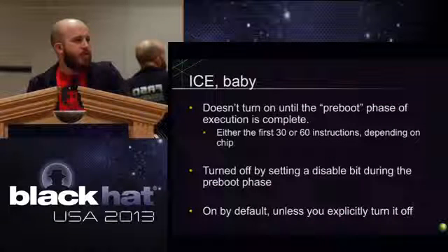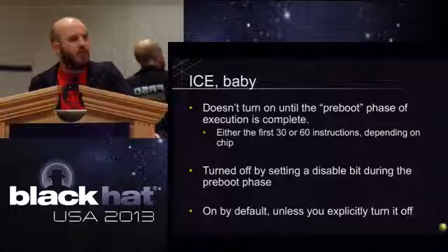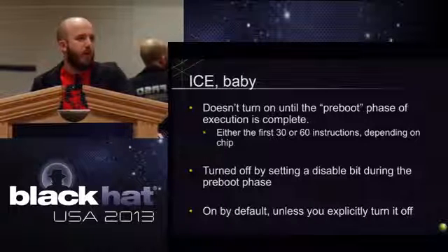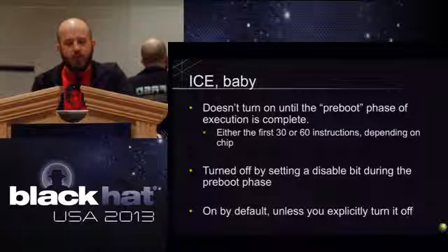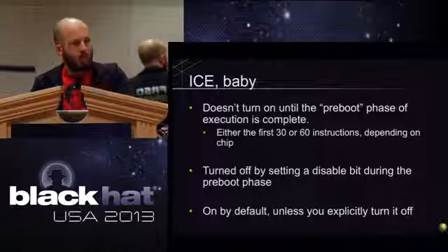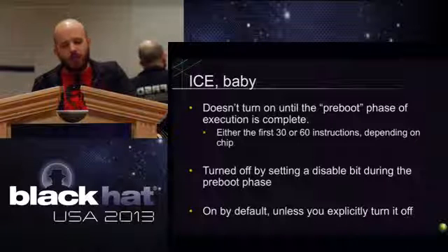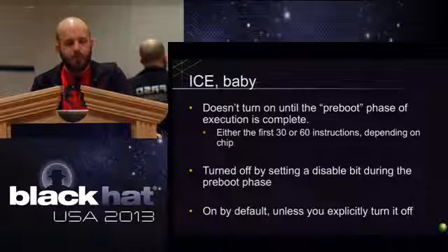So the way this works, you think about JTAGs, right? You know that JTAGs have these fuses, and you can blow a fuse, and then the JTAG interface is now turned off. In this case, it doesn't quite work the same way. It's not on whenever you first turn on the machine or first apply power. For the first 30 or 60 instructions, the processor is in what's called the pre-boot phase.